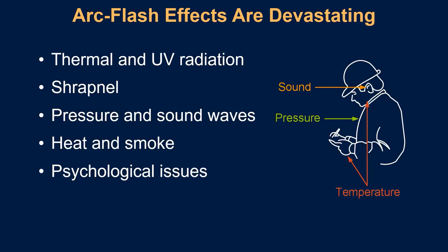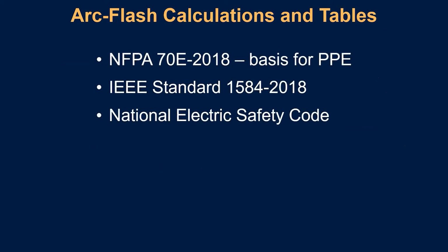And so what are the standards governing arc flash, and how do we evaluate this risk? So talking about arc flash, there are mostly 3 major standards. To start with, the NFPA 70E, the National Fire Protection Association standard. They provide specific guidelines on safety, including how to mitigate arc flash hazards, and also provide guidelines for selecting personal protective equipment.